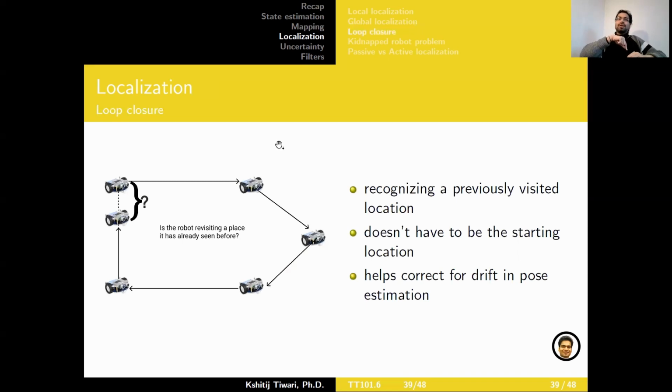As long as you recognize that you are revisiting one of the places that you have visited before, through any sensory feedback that tells you this, that is known as a loop closure, and the robot needs to be able to tell, oh right, I remember this place. So it can suddenly relocalize itself in case it gets lost. That's like your safe zone. So imagine you're exploring the environment, you think you know where you are, right? So you keep going somewhere, and then something happens.